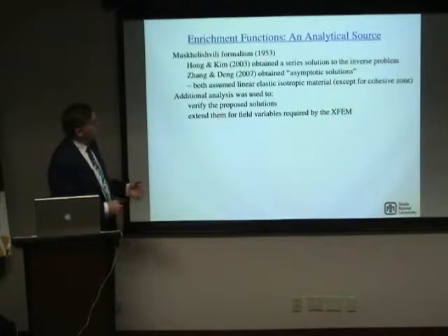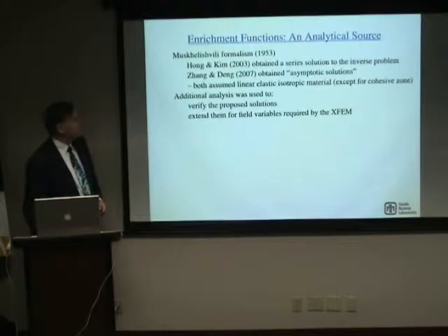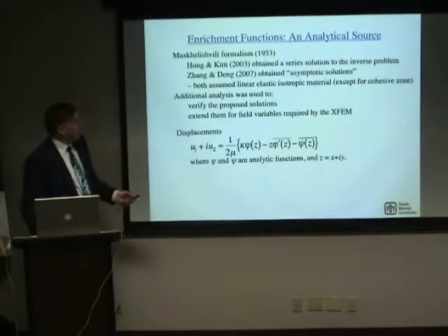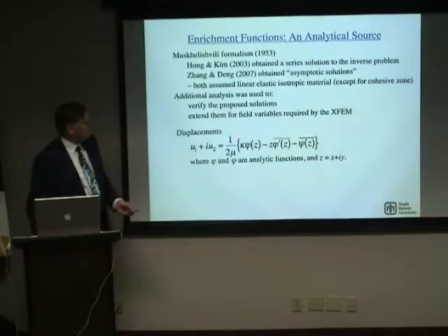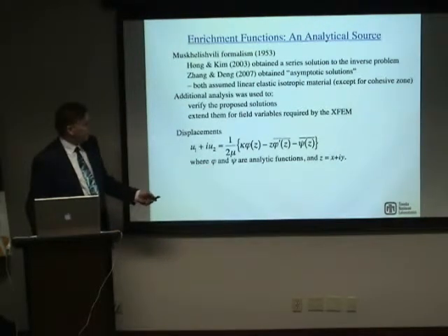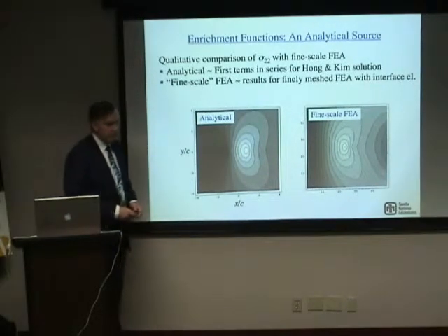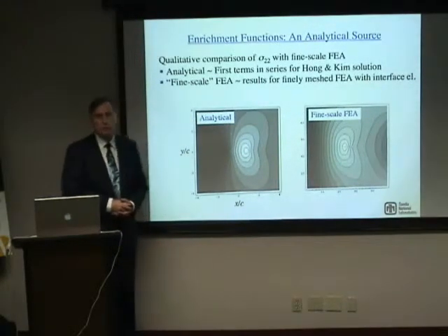Yeah. There's a fair amount of work in taking the analytical work that they had done and coming up with enrichment functions that can be used for the crack problem. And all of them, as I mentioned, are based upon the Muskhelishvili formalism, which writes the displacement field as a complex field in terms of two analytic functions. In the case of the crack problem, they're analytic over all of the domain except where the crack is. So you have to come up with an expression for these. In general, they use series type solutions in both works.